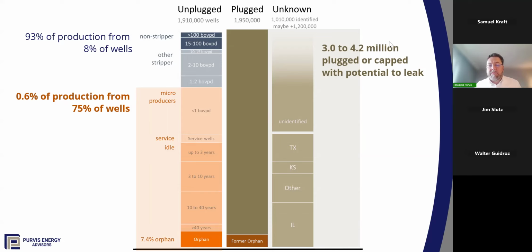So to deal with these 2 million wells that are still waiting for us, and the fact that we delayed plugging those may prove to be beneficial, because now we have the chance to change the paradigm that we use to plug them. And by all accounts, cement is a good base material, but we are using it only in a fraction of the wellbore, and it is brittle.